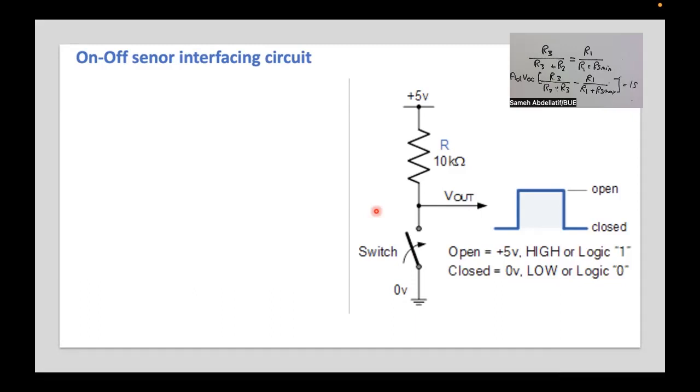So it's something like a pad distributed, or put on the floor of the room. If you press this piezoelectric material by your weight, the material will work and will make some sort of a resistance. Otherwise, if no one is here, then there is no pressure, then it will be an open circuit, for example, or a very high resistance. So this is a very typical example of an on-off switch using a piezoelectric material.